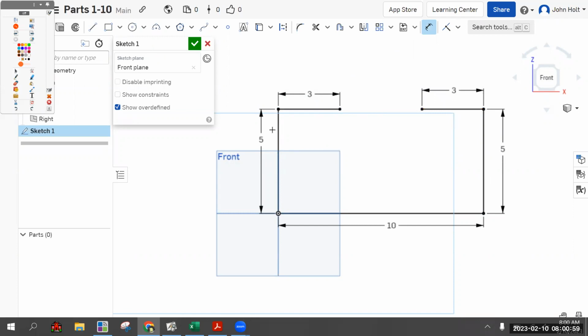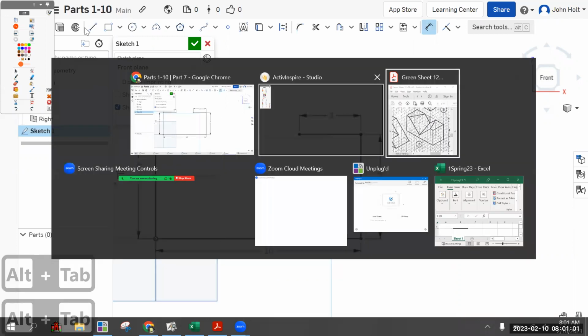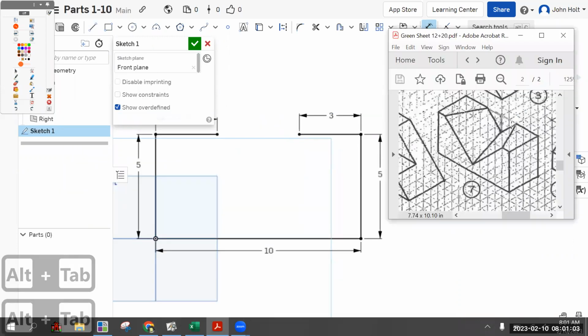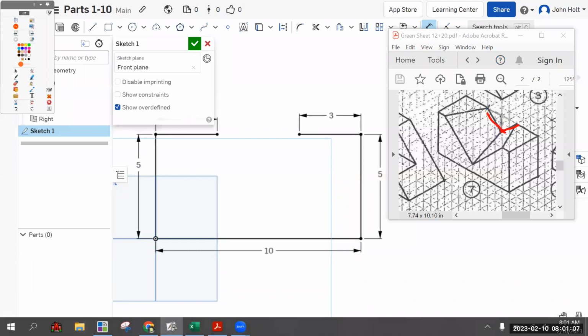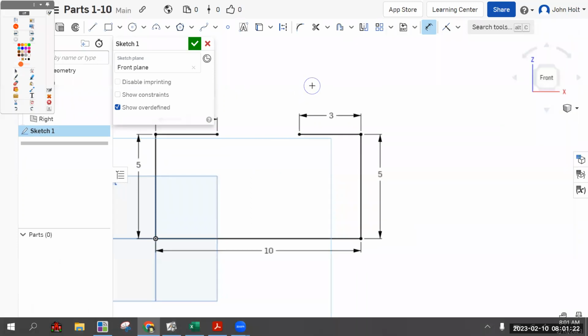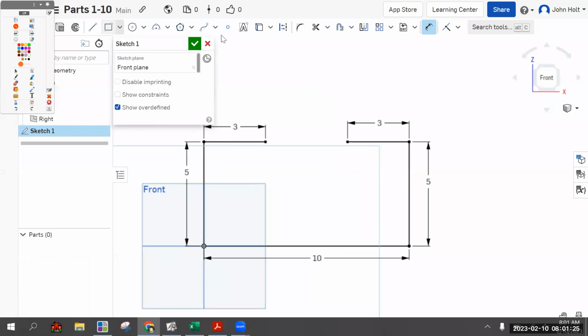Okay, and then like I said, we need to find this point, because in order to do the slope lines, we need to know where it starts and where it finishes. We know where it starts, these 2 starting points, but we need to find this point exactly in order to do the sketch. So there's a couple ways to do this. We have work point?